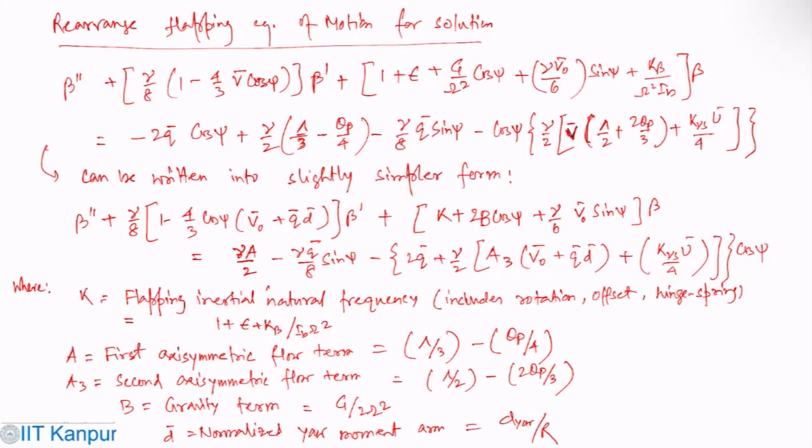so what we have now, this equation actually includes all the forces, I mean, essentially includes all the restoring forces and all of the forcing terms. And now this can be used to find out the rotor behavior under a variety of wind and dynamic conditions. So this is complete, this equation that we have here.